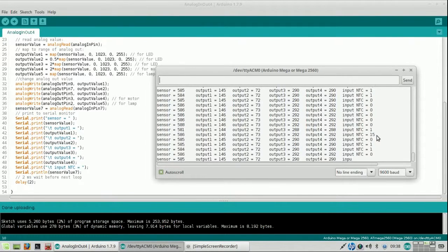Okay, the fan is now switched off. Very low temperature. So, and the lamp very close to the NTC again. So the values are a mystery to me. Now the fan is at the strongest. Low temperature should be high resistance, and I can't verify that, not with the values I'm looking at.